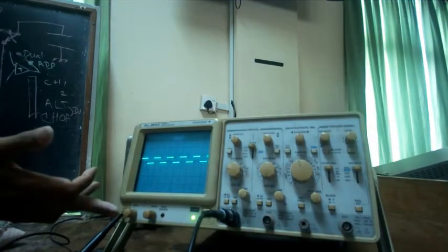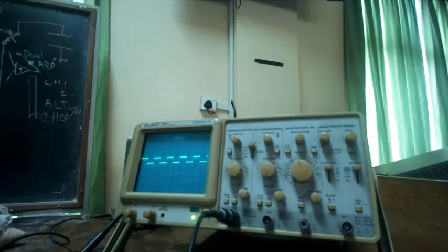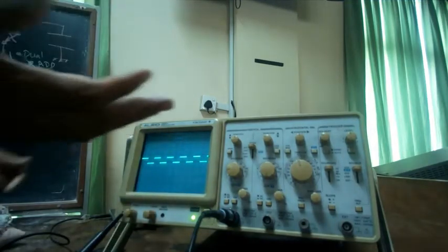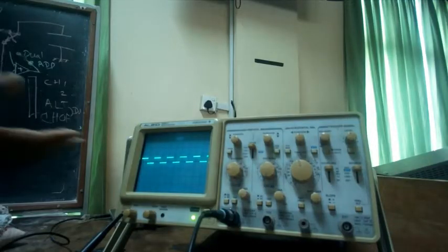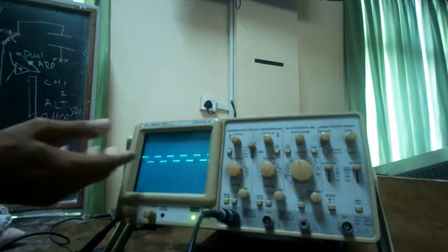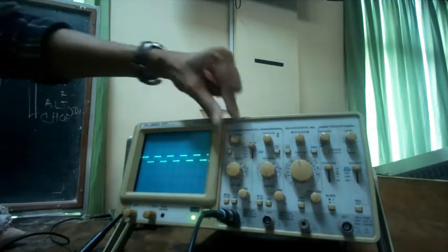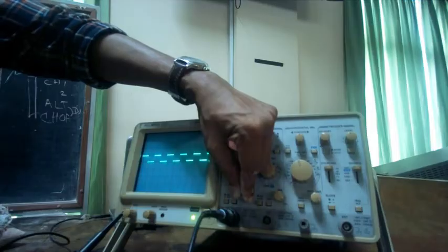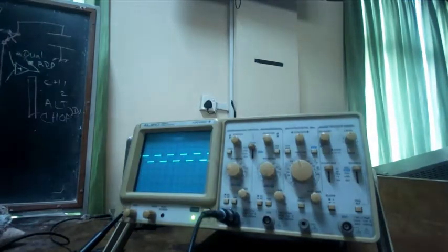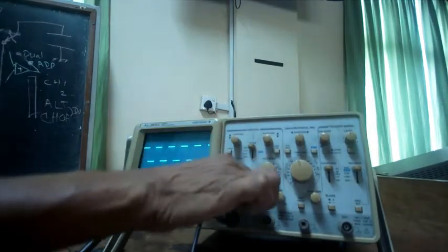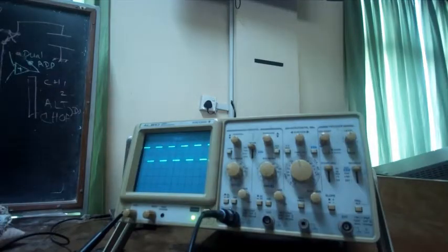Not because my source has changed. The source is still 2 volts peak to peak. But my output screen does not represent 1 volt per division now. In this case, it's about 0.8 of a division. 0.8 division is equal to 2 volts. If I want this to be 2 volts per division, it's like that, right? So whenever you make voltage measurements, make sure that you have it exactly at the cal position. Otherwise, your measurements will be wrong. Is it clear? That's something very important that you need to keep in mind.